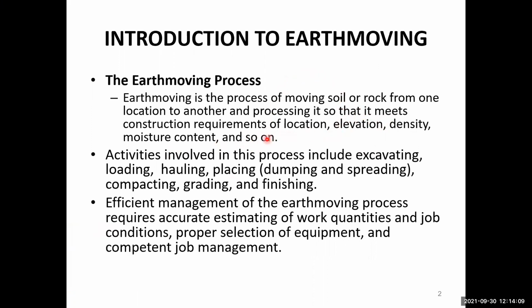So therefore, earth moving operation is not just moving the soil from one location to another for no reason. There is a reason for moving the earth from one location to another, because we need to prepare the site for the construction work to be performed. And of course, the soil should be of the desired density. If the soil is of the desired density, then we will be able to strengthen the soil to our desired level, so that the soil will have enough bearing capacity to withstand the loads of the construction.